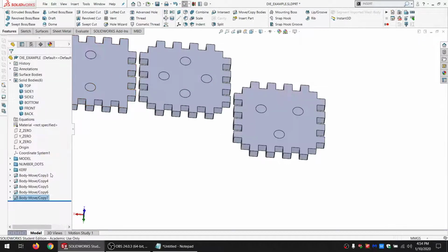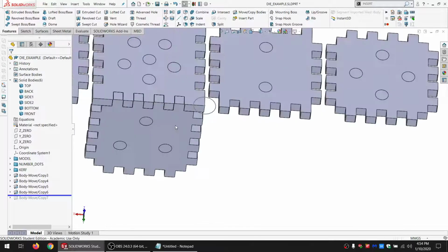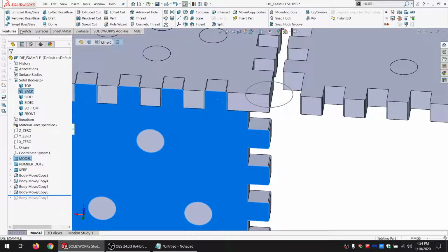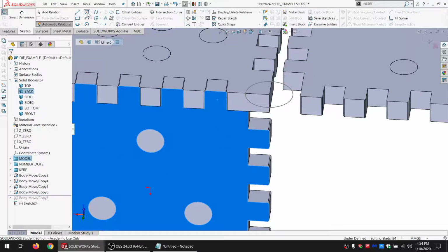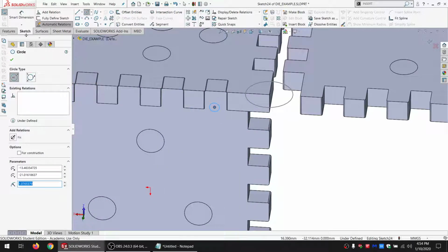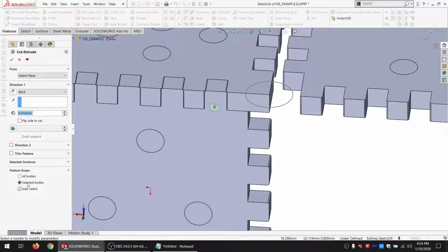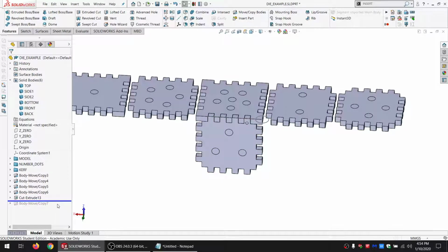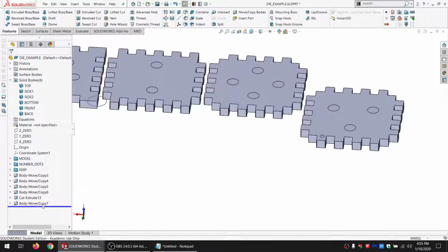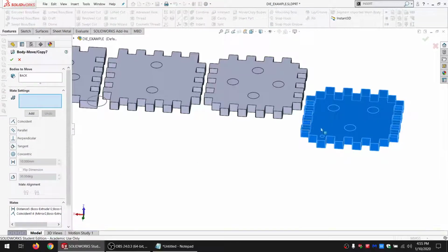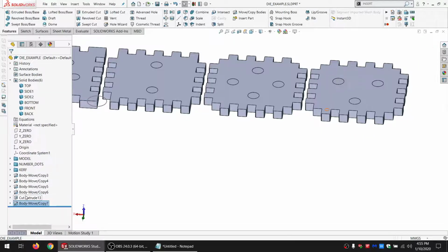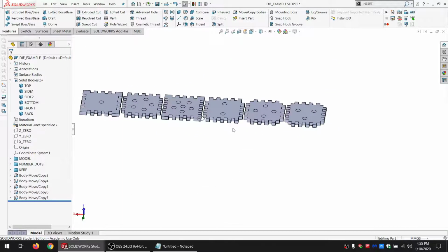And this can get confusing sometimes, so we're going to roll back before it. And so this is always going to be there. To make things easier on myself, I'm going to put a little mark there. Just extrude cut. Sometimes when you're flipping things around, you get confused so easy. So just putting a little mark there, roll that forward, modify this one so it's there to there. Okay. And with a little bit of luck, when I delete this, it won't freak out. Okay, it's fine with that.